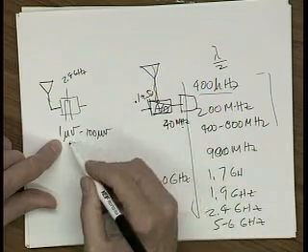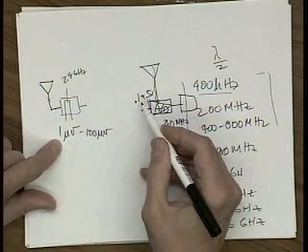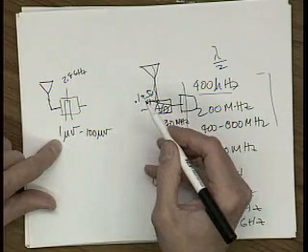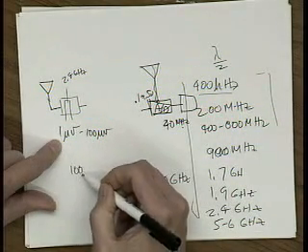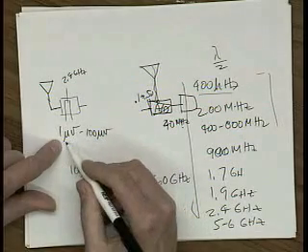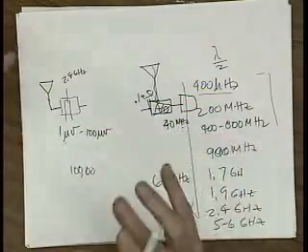100,000. If it was 1 microvolt to get up to 100 millivolts, 1 microvolt to a millivolt would be a gain of 1,000. To get up to 100 millivolts would be 100,000. So you need a gain of 100,000 for the really small signals; larger signals may only have a gain of 1,000. So you need a lot of gain.